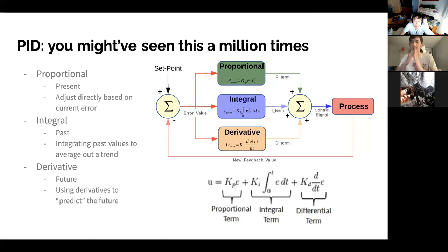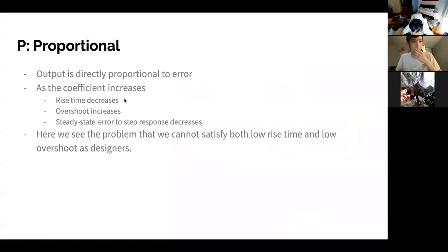But when it's at the line, you actually want it to move this way. So if it's moving to the left, we don't want it to move to the left anymore, and that's what derivative does, because it predicts in what direction it's about to go. Especially in inertial systems like we have, the derivative is a good variable for that.